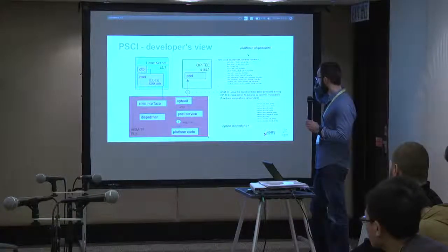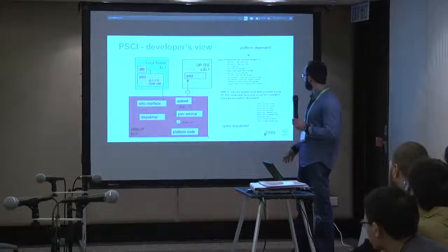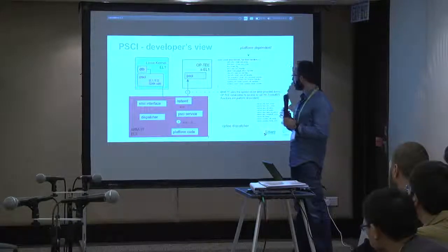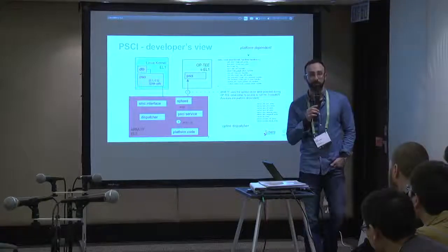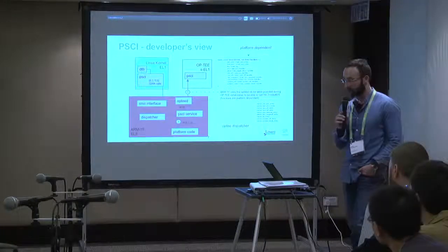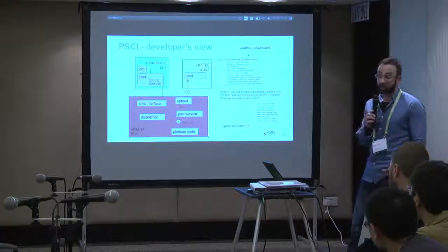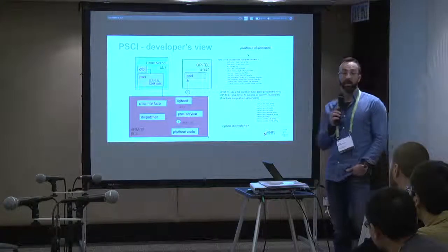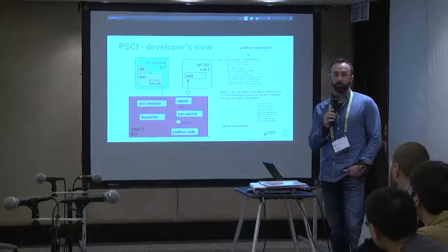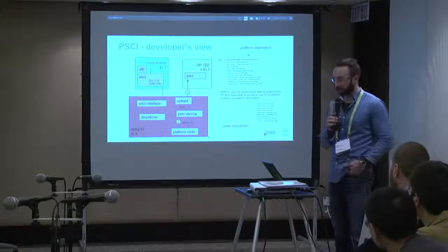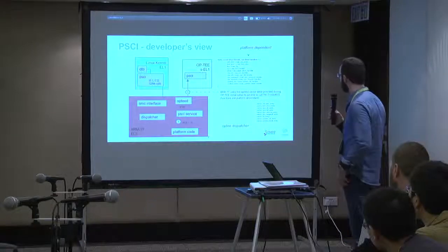In terms of how the interface is handled, I thought it was relevant when I was looking at the code. This is the way the interface is handled. So the ATF uses a vector table to find out where to call and how to call the OP-TEE. PSCI doesn't define the way the interface is put together, so it doesn't place any restriction on how to call a trusted environment. It just says every vendor can do whatever they want. This is the way that the OP-TEE was done.